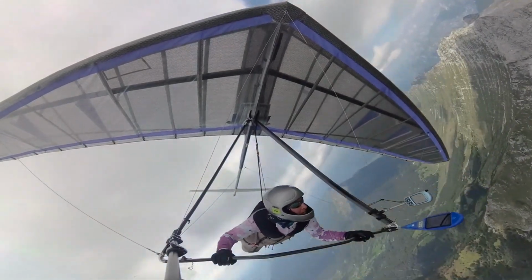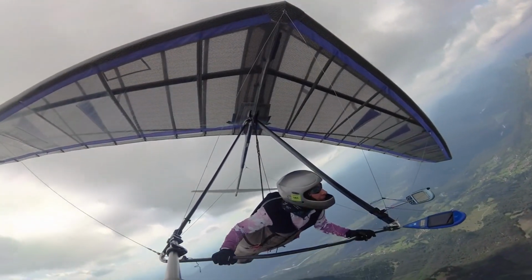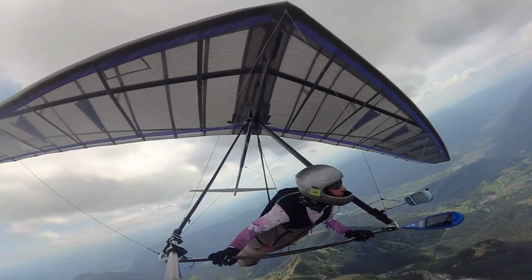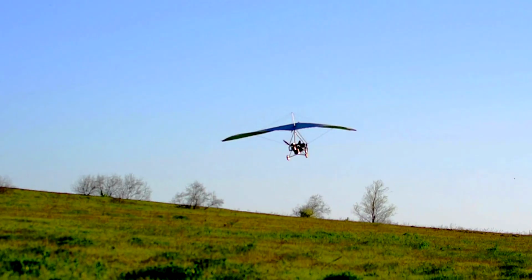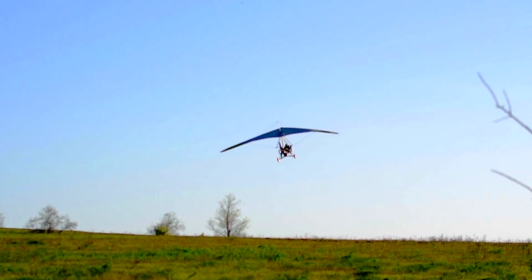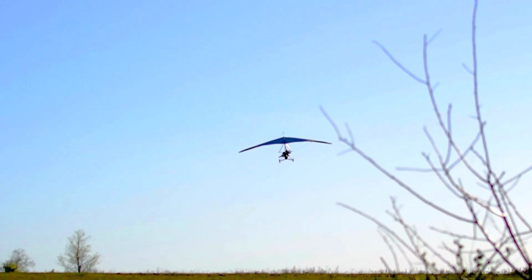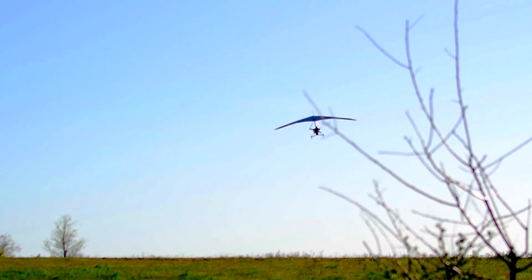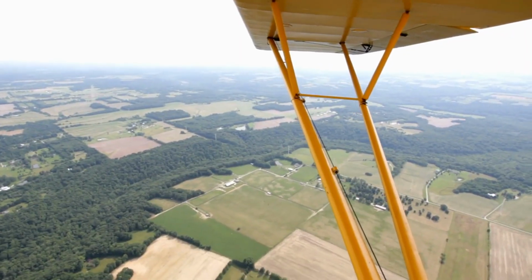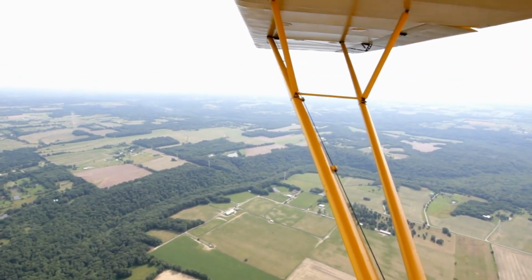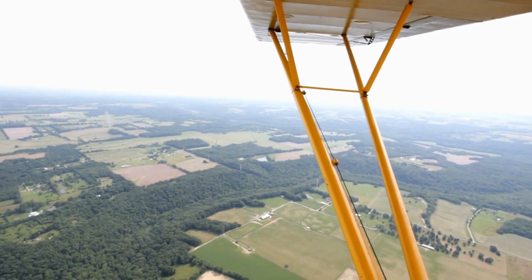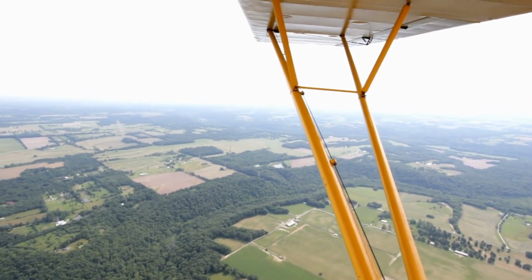Secondly, the wing is designed to flex as it changes and twists from side to side for turning, a concept historically known as wing warping. Unlike the traditional use of wires, the WSC aircraft achieves wing warping by shifting weight, as detailed in Chapter 3, Components and Systems. The term flexibility, in this context, does not imply a lack of rigidity but highlights the adaptability of the wing structure to enhance flight dynamics.